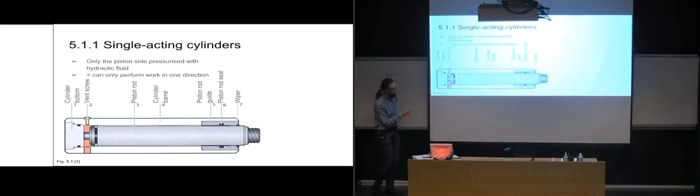And then you would risk having a lot of leakage out there. Not that much leakage in this case, because you're not going to have any hydraulic fluid coming into this area, but in a double-acting cylinder, which we're going to look at on Wednesday, you would have a lot of pressure loss going out here, and you would have hydraulic fluid everywhere. It would leak out.